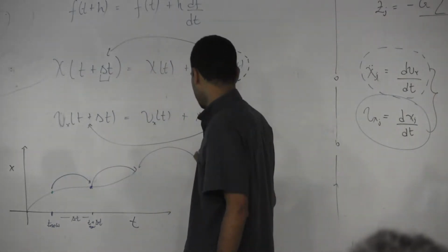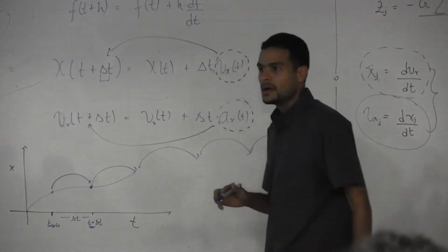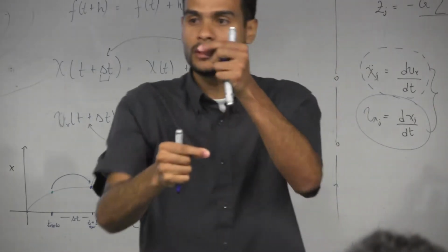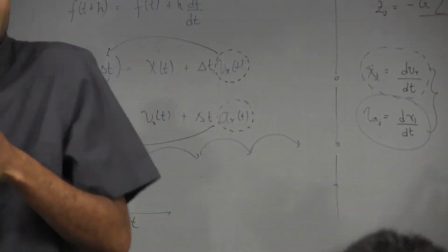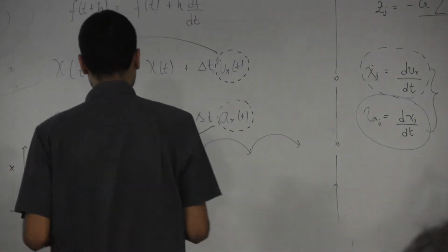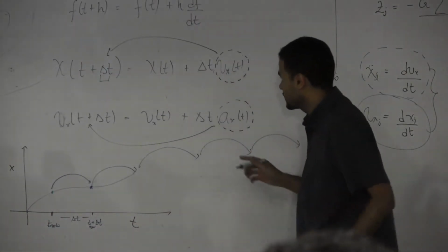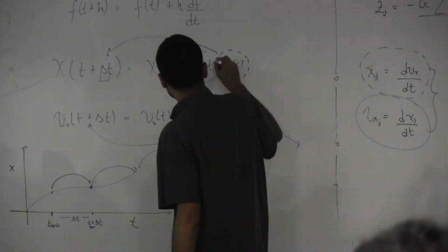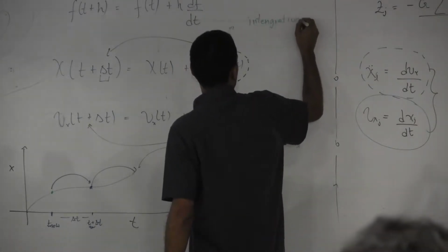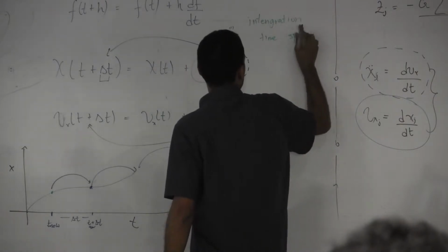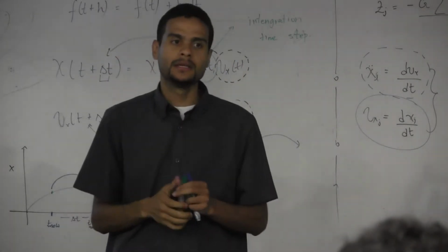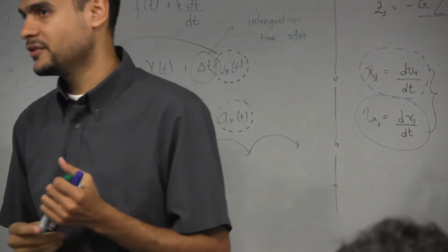And then I move, and I do the same, and I do the same, and I do the same. And second by second, I can then compute the position and the velocity of each particle in my simulation from now till tomorrow, or until whatever, which depends on the length of the problem you are solving and its characteristics. This delta t is called the integration time step. It's a very important and critical quantity in numerical solution of differential equations.